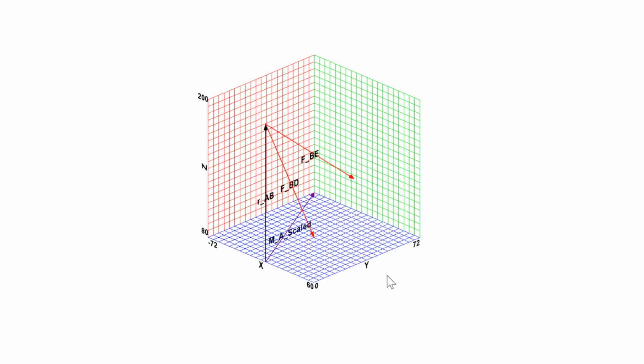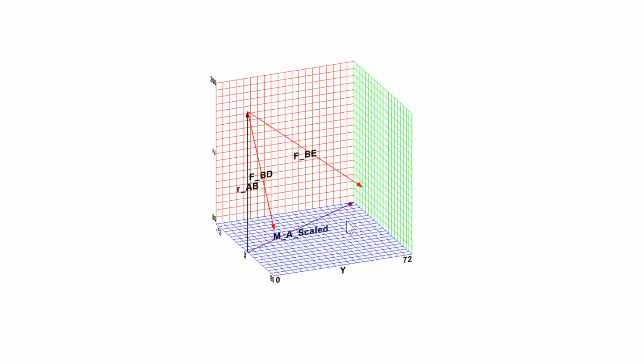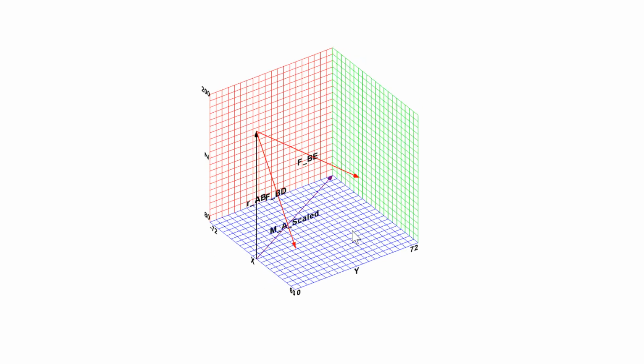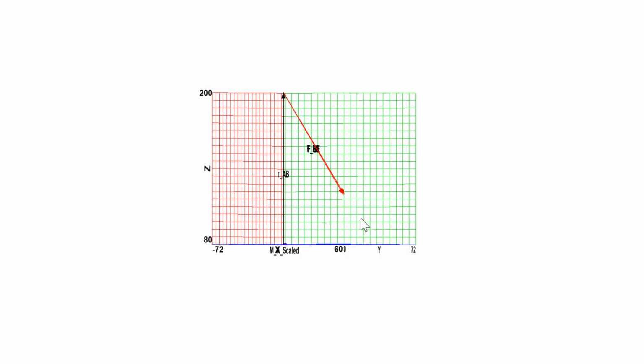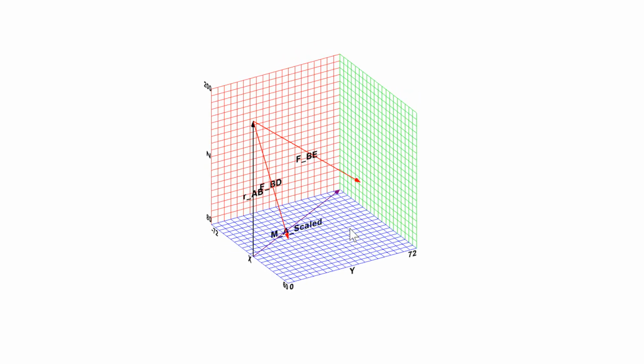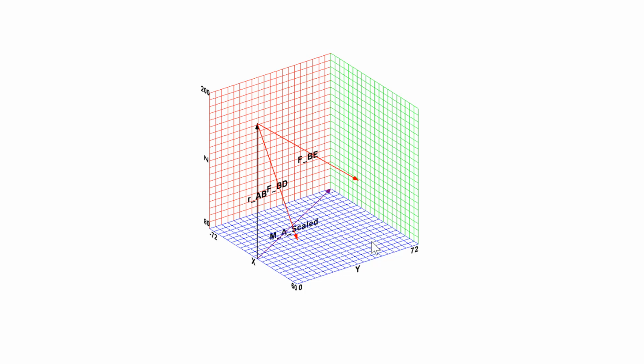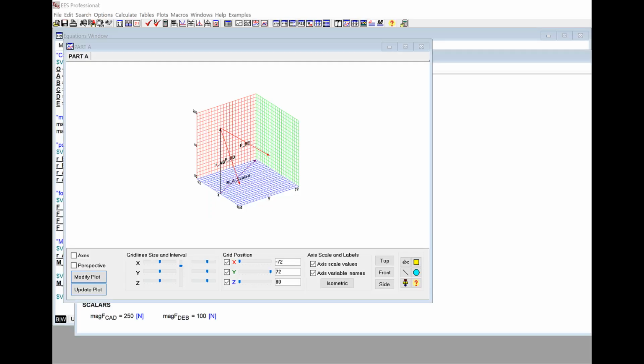So at this point I should be able to solve, and part of the solution then will go through and build that vector plot. And you can see here, here's the structure RAB, and then these are these two forces, and you can see they're tending to twist the structure right around that moment, right? So that's what the moment is. It's the axis that the structure is being twisted around. And I think this makes it a little more physical what these moments mean.